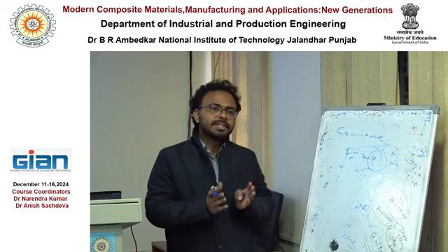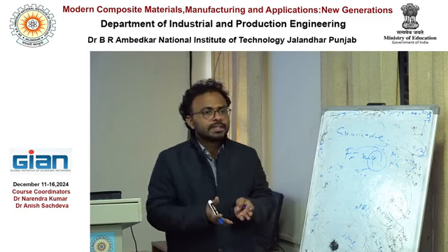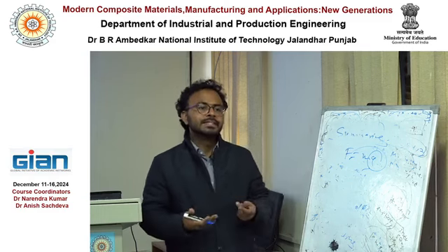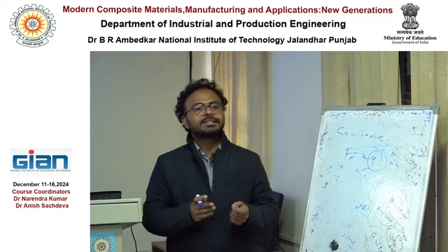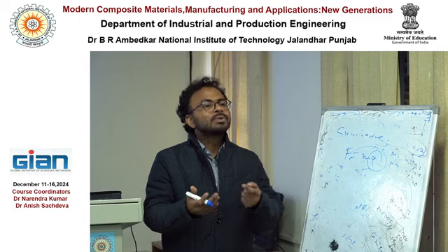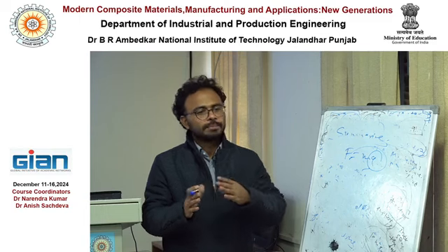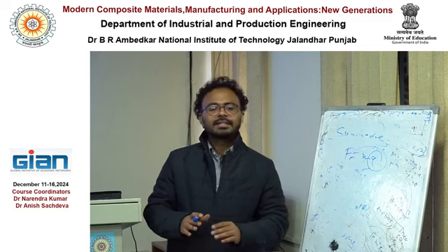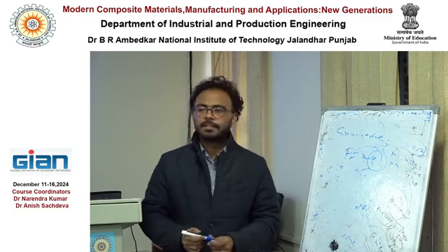But the implicit one, static one, has no much difference; quasi-static one is simple. So the inverse of the matrix is possible very easily, right? So this is the way. That's why I said if the velocity is less, use implicit more, then go to explicit. So the explicit gives you the answer, although with 4 to 5%, 6% error, but at least you reach somewhere. Rather than no answer, you can have some answer.